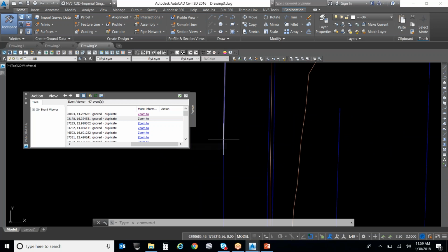It's right in there. So there's actually a point and a break line. So it's using the one that was added first, okay? It's ignoring the duplicate. Duplicates are okay because it's ignoring them. It's when you have a difference of elevation because the duplicate wasn't the same elevation as what was used, okay? So again, if you're using contours, you'll get a different elevation if in fact they've smoothed the contour out, okay?